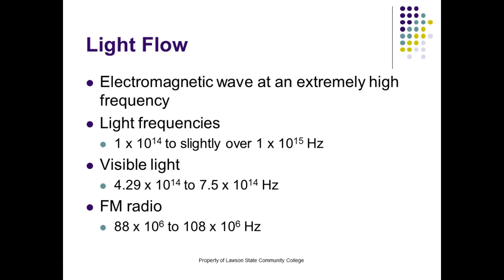So the technique of putting a signal on another, higher frequency waveform is called modulation. And so we have what we call a carrier. It carries the information. And then when we get into our radios, we strip the carrier off. Somehow we strip the carrier off and let the information come through. So the two primary ways are what? We can modulate the frequency, or we can modulate the amplitude.